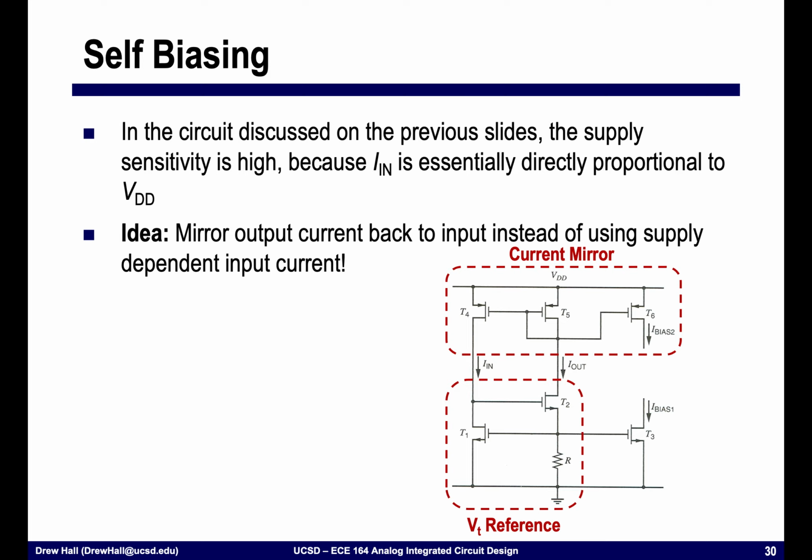And if you go back to that example, the reason that we had that high dependence was that first prefactor being 1. The second prefactor was that 11.5%, and so it reduced that prefactor of 1 by 1/8 essentially. And so the question is, is there a way to better generate that input current that is not quite so dependent on VDD?